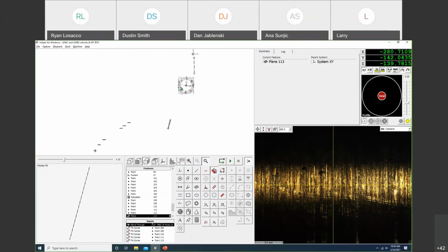And if you did a distance from this plane to the original origin, we weren't getting the number because they weren't angled correctly together. Instead of looking at the same angle, it was looking straight down, which created a larger distance between the two. So we needed to flip the working plane, so we were looking in this direction.